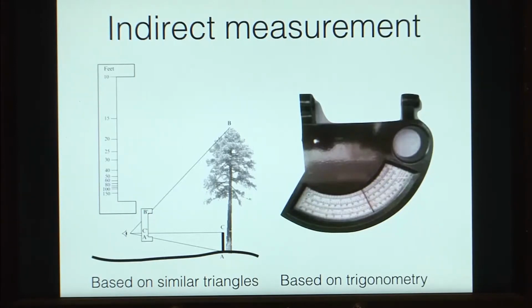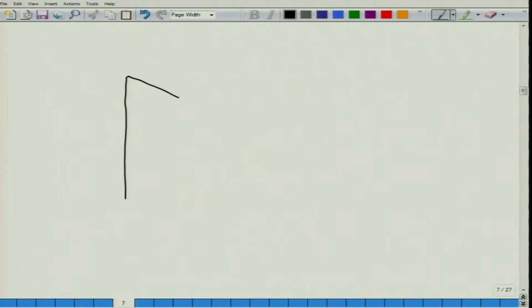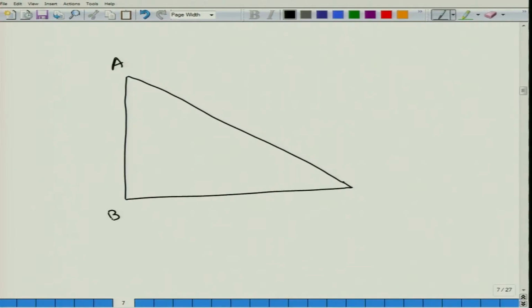So, what we do in this case is that in this triangle ABC, this angle is theta, we take this distance d to be a constant. So, while using the instrument, we can take this d to be equal to say 10 meters or say 20 meters, depending on the scales as are given in that instrument.